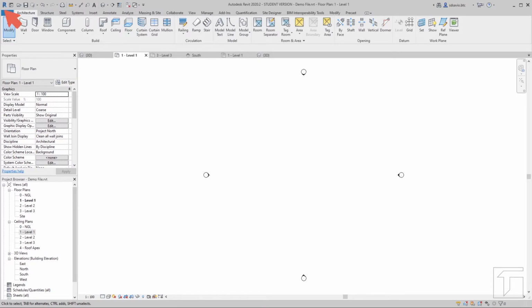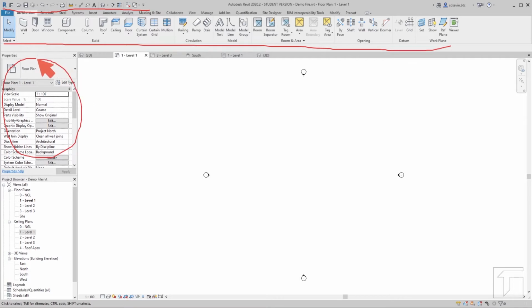on the top you will see a quick access toolbar, so the icons here, which you can easily access when you need them. Then right below that is the ribbon menu. So these are the main commands which we'll be using when we will be doing some modeling or drawing here in Revit. Over to the left, we have this properties palette, this one here. The properties palette holds the different characteristics when a command is executed. Okay, and then right below that, we have the project browser.